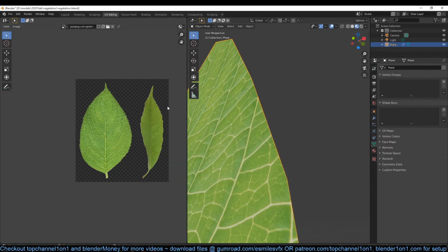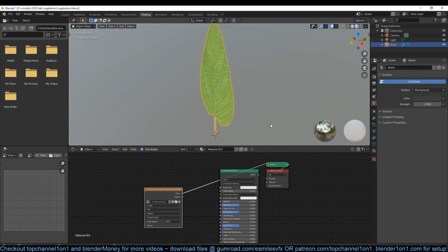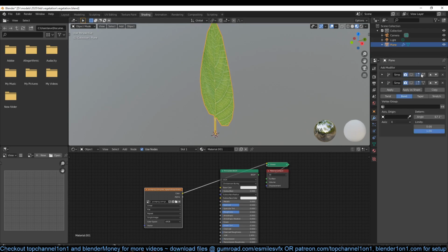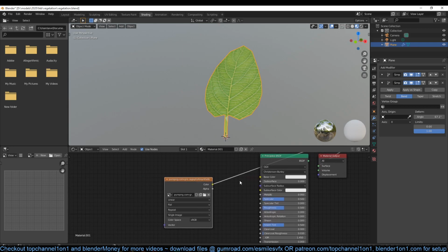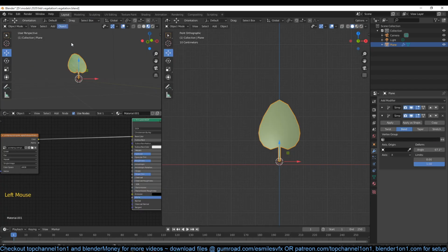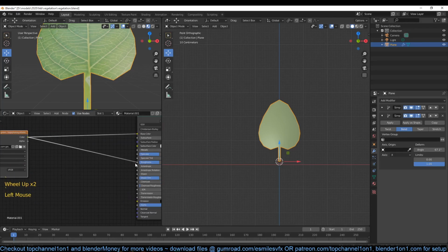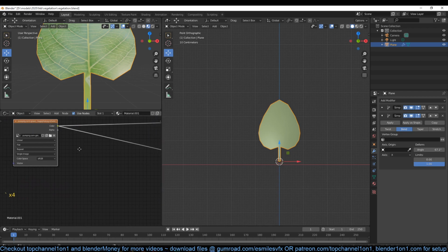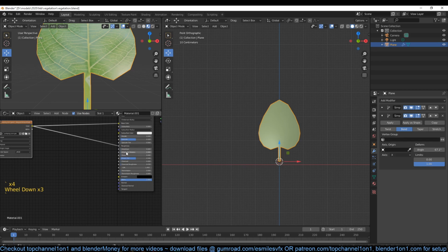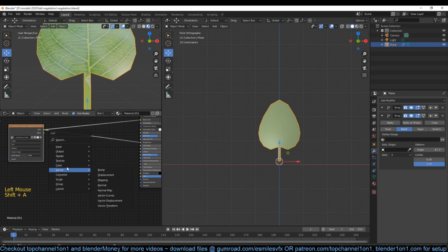So now after we have the material, we can just go in and tweak it a bit so that it looks nice in our renders. Also, let me now turn back my modifiers. Just going to connect this to the base material, preview this. Let's go back to my layout. Then what I can do is connect this to the roughness. You can find PBR materials and then connect the different texture maps directly into their material inputs. But since I only have this, I'm just going to use it for everything.